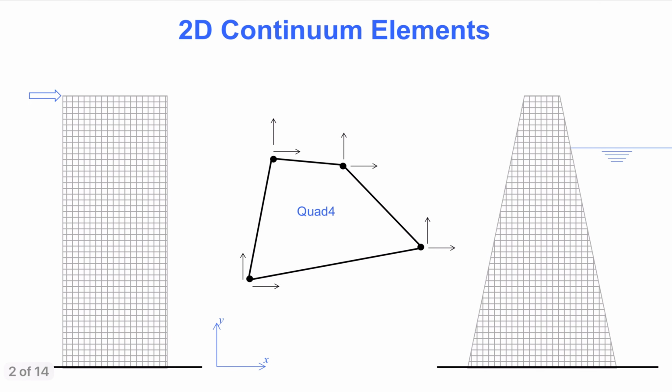It is helpful to learn the computational stiffness method as a foundation for learning the finite element method. However, it is only with the consideration of an element like the 4-node quadrilateral element, shown here, that we get exposed to the full-fledged finite element method. Not only does the finite element method for this element give us solutions that we could not find in other ways, we also get exposed to concepts like two-dimensional shape functions, the isoparametric formulation, integral transformation, numerical integration, and the consistent load vector. Those are topics addressed in this video.